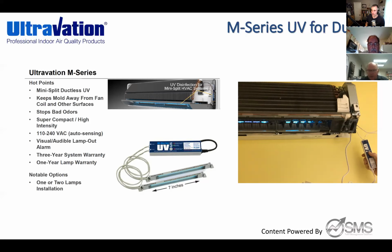So we said, great, let's take our UVC wavelength bulbs, make mini versions of them. We surrounded them with some directional shielding, so you can make sure the light only shines one direction. So depending on the manufacturer, you might be able to fit these up behind the coil. Maybe you have to fit them down lower and then shine the light straight up towards the coil. Some guys are shining them out at the blower wheel. It's up to you guys in your design, but that's a universal kit. It's got an auto sensing power supply, so it doesn't care if that was wired for 110 or 240. It'll find what it needs, lights the bulbs up, and you're good to go.